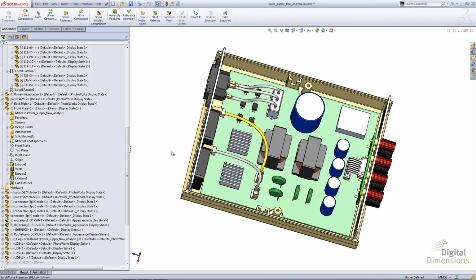The component now will become virtual. We indicate that it's virtual because of the brackets that show up within the name of the feature tree. Now, behavior to take note of: external files within the top level of the assembly are candidates for becoming virtual components. If you have components that are within the subassembly, you will have to open those separately and then make those virtual in turn.